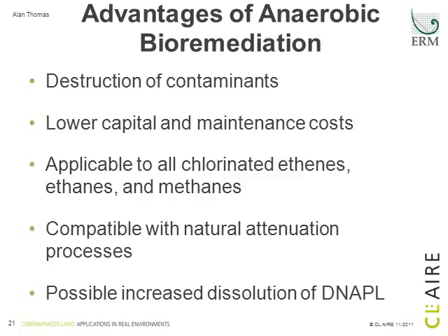It has been used to address DNAPL source zones, and it will result in increased dissolution of those source zones, and in fact that's what it's trying to do. That's the result of injection or optimization of anaerobic degradation. It's creating a dissolution gradient that's resulting in the increased removal of the residual NAPL into the dissolved phase where it's degraded.